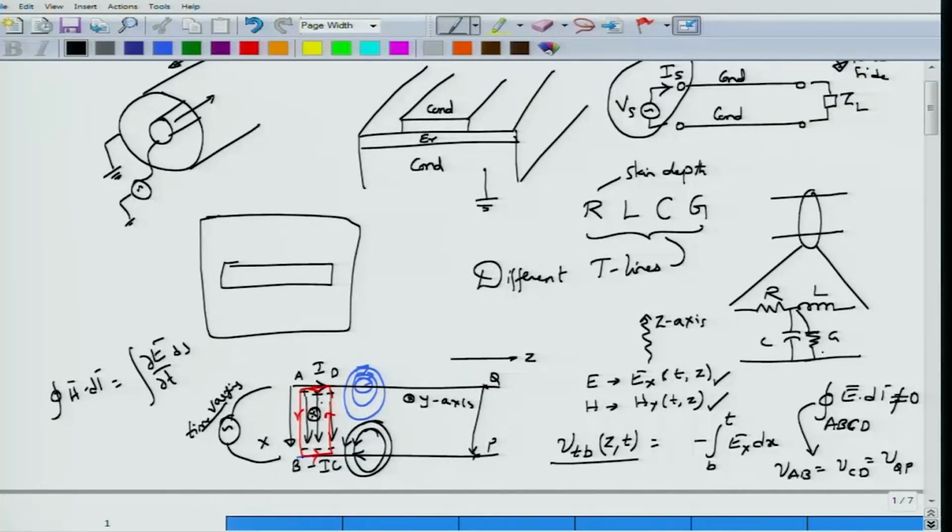So the space between the transmission lines actually supports a wave, and the solution of the wave equation, if you describe that particular region by a wave equation, will turn out to be plane waves. Okay, and energy is actually carried not by the voltage or the current along the transmission line, but rather by these electric and magnetic fields, by the Poynting theorem. So in fact, energy is not transmitted from one point to another by the transmission line, although its name would suggest that, but rather the transmission line simply acts to guide the electric and magnetic fields in order to carry energy from one point to another point.